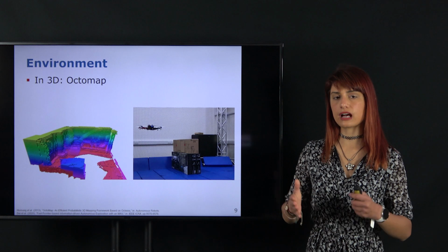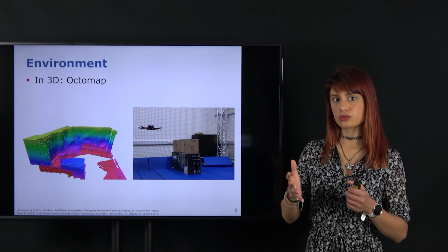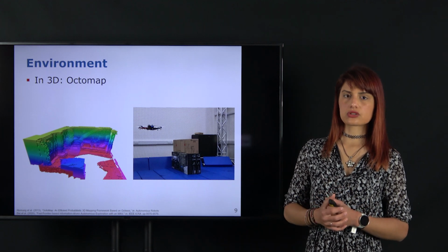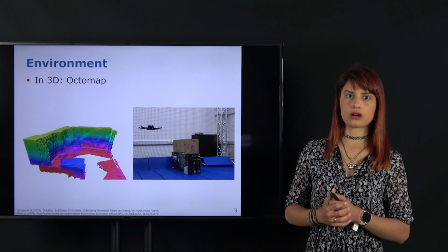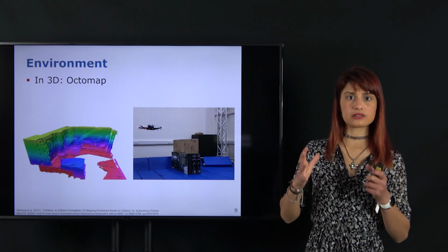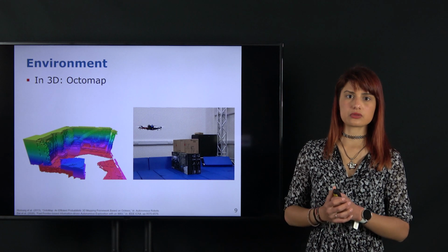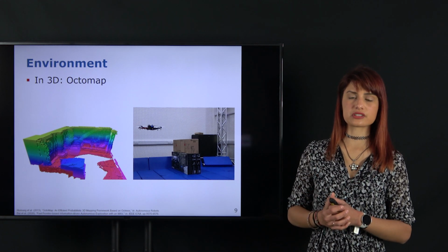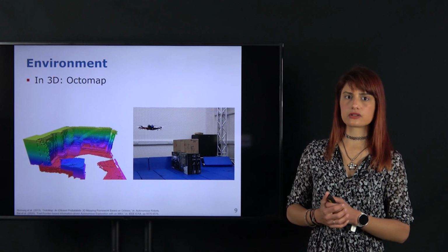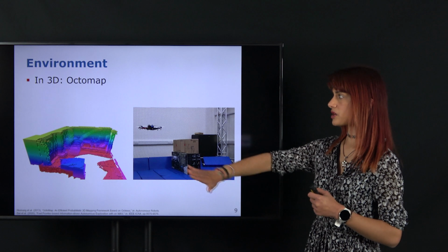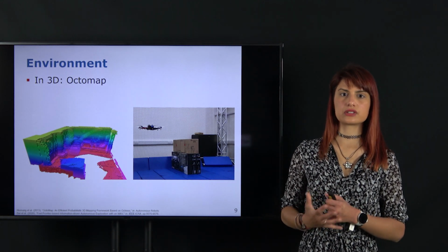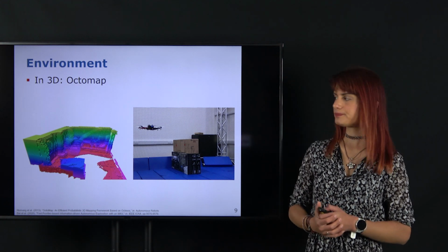For example, if we have a narrow passageway that the robot can just squeeze through, we need to make sure that the resolution of our grid for path planning is such that it does not obstruct the space, but rather captures the free space as well. These are just some considerations to take into account, especially moving on to the 3D world, to make you aware that we need to consider more efficient methods.